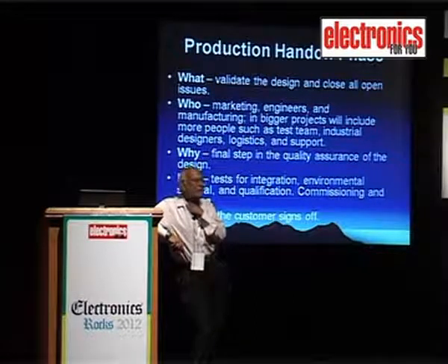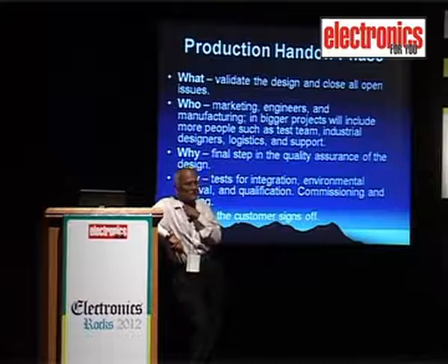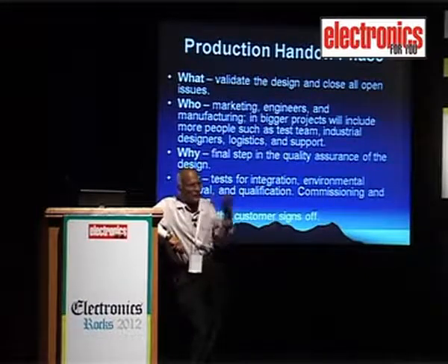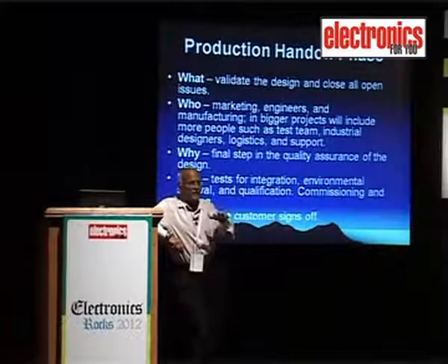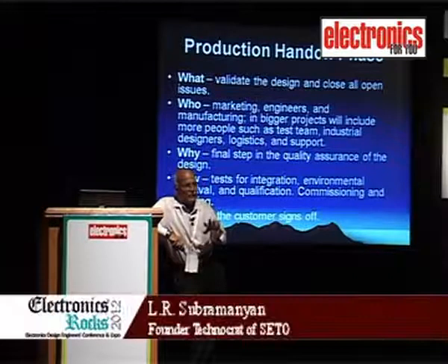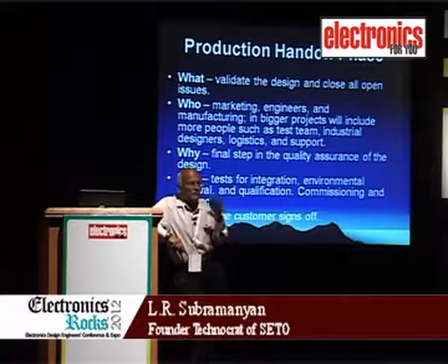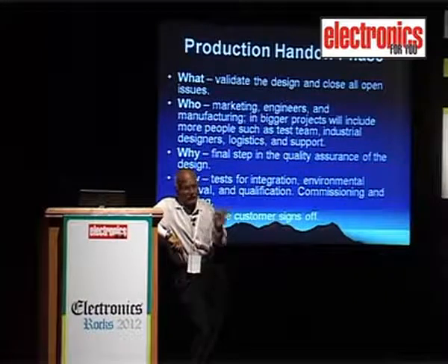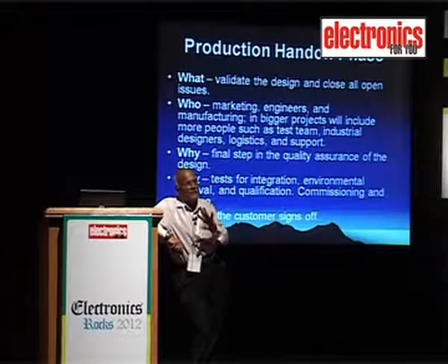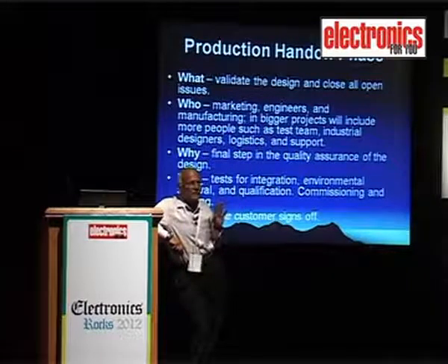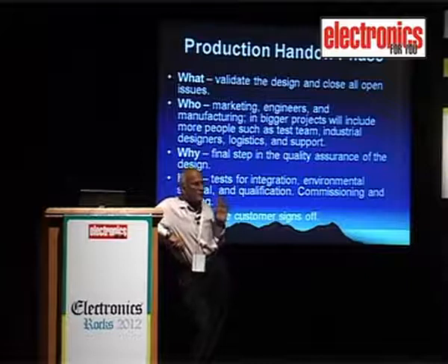It took us nearly 4 months of validation to ensure that if an operator remote controls, if I give an on signal, the breaker will become on. If I give an off signal, the breaker will become off. If by chance I give an off signal to a breaker which is off, and it becomes on, somebody may be working on the line and he might get electrocuted at 11 kV or whatever.